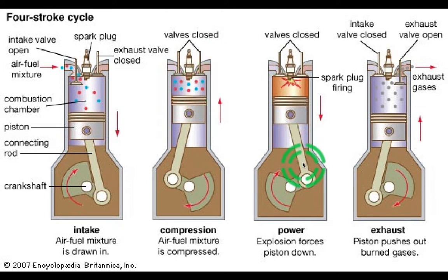Then we move on to the third stroke, which you call the power stroke. When it's on top, TDC again, top dead center, both valves are still closed. Then the spark plug is commanded by the ECU, since we are dealing with a modern fuel injection system.